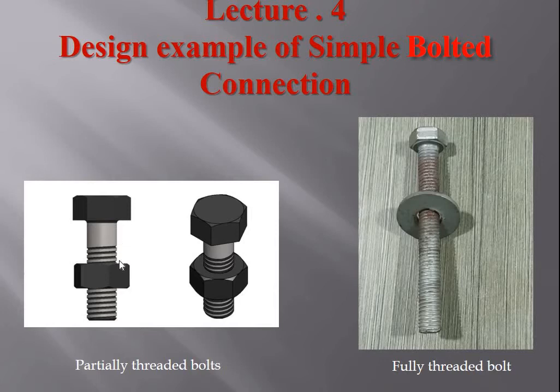And ANB, the net area of the bolt, is reduced over this plane section due to the threading. That reduced area is considered by the code as 22%. So the remaining net area of the bolt is equal to 0.78 into pi by 4 into 20 square, which comes out to be 245 mm square. But we put the value of NS as 0.